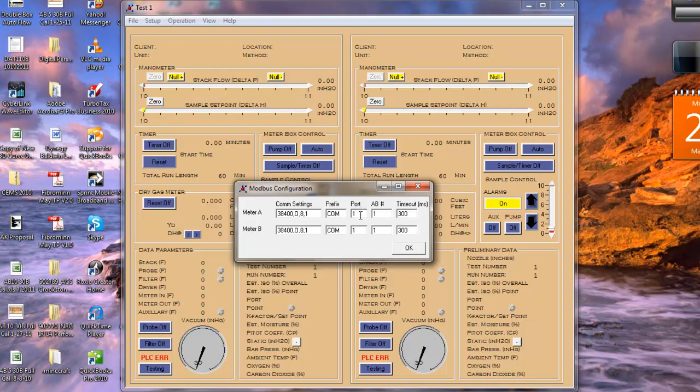And here we have the port. The port is either the USB or serial port that's being used to communicate with the Autobox. So in order to find that out, typically we're plugging in a USB to serial adapter, which is a small adapter that would plug into a USB port and then connect to our cable running to the Autobox. So we need to find out when you plug in your USB adapter, the computer generally assigns it its own number.